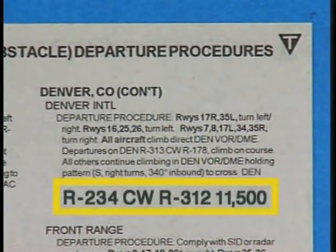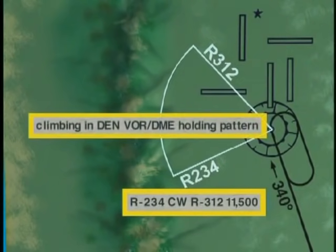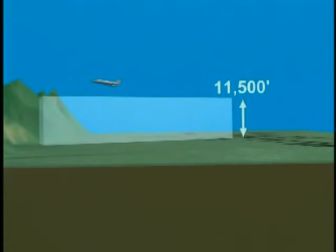Note the altitude requirement for aircraft departing westbound from Denver between the 234 and 312 degree radials to ensure obstacle clearance. If you're flying this textual DP for your initial departure, you must climb in the Denver VOR holding pattern until at or above 11,500 feet before proceeding westbound.